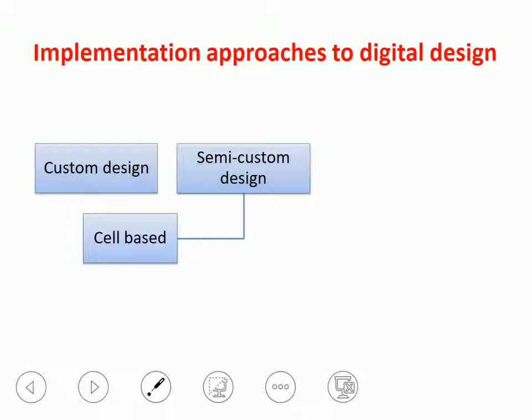With semi-custom design, we have really many different possibilities. One possibility is the so-called cell-based semi-custom design. In that case, we use the so-called standard cells, which means that we have a library of individual cells, for example, logic gates, buffers, or sometimes also analog blocks that are needed for the operation of the devices, input-output blocks, etc., that have been pre-made, have been put in a library, and must only be used. This library is called, of course, a library of standard cells.